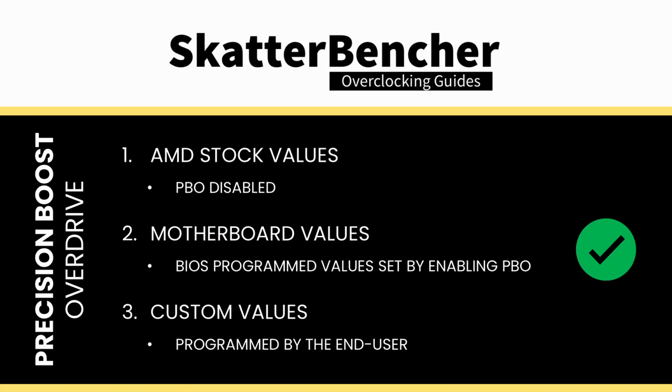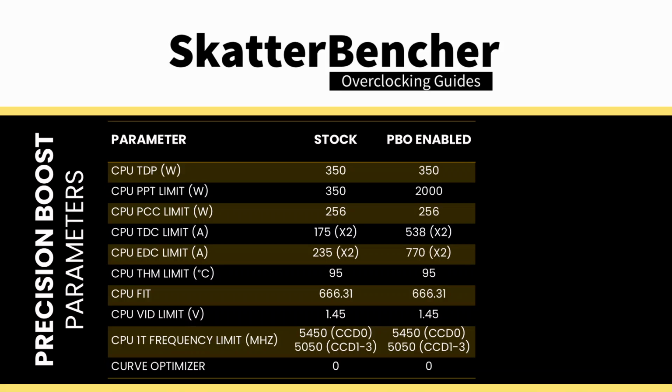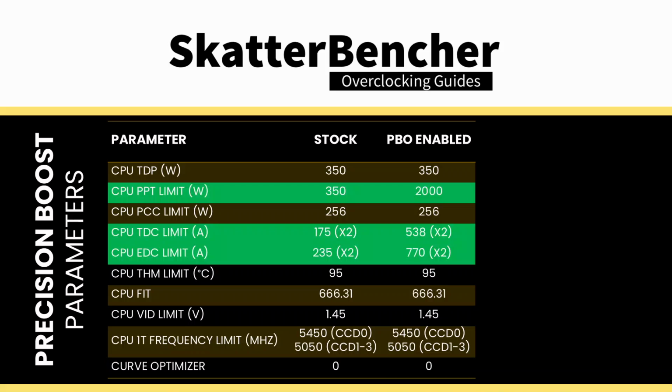By enabling Precision Boost Overdrive, we rely on the motherboard pre-programmed PBO parameters. We find that the following values have changed. Increasing the PPT and to a lesser extent the TDC and EDC limit will help unleash the frequency in multi-threaded workloads previously limited by the power.